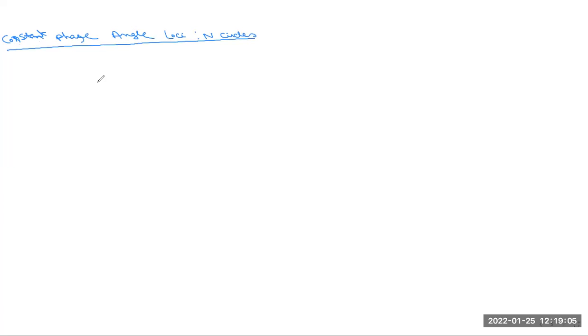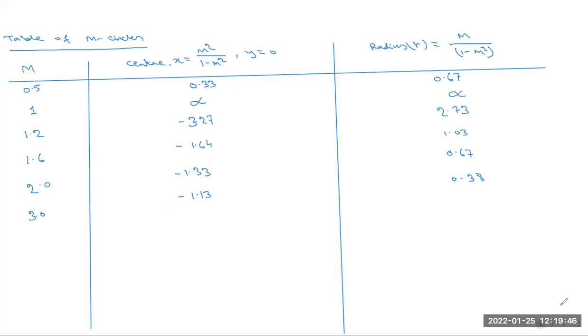Okay, this is another part. So when you consider the closed loop function for the unity feedback system, that means H(s), that is H(j omega), is also 1. So now in the previous equation, I just wrote the equation. Then you have to remember. We know that M equals (x plus jy) by (1 plus x plus jy). We have derived this in the previous equation.